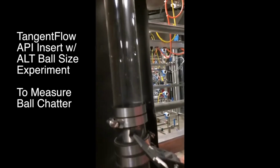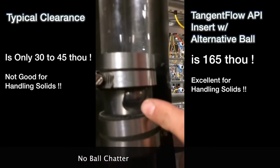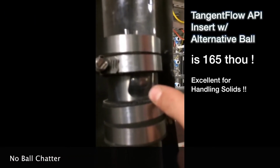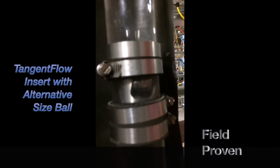Hi, I'm Corbin Coyes from Tangent Flow. Here's an experiment with a 1 3/4 API insert with an alternative ball, and you'll see it's going at 20 gallons per minute, and it is not rattling and seated perfectly. This is the ID of the ball. It's a 1-inch alternative ball. The ID of the 1 3/4 insert is 1.165. There is 165 thou clearance between the insert and this alternative ball.